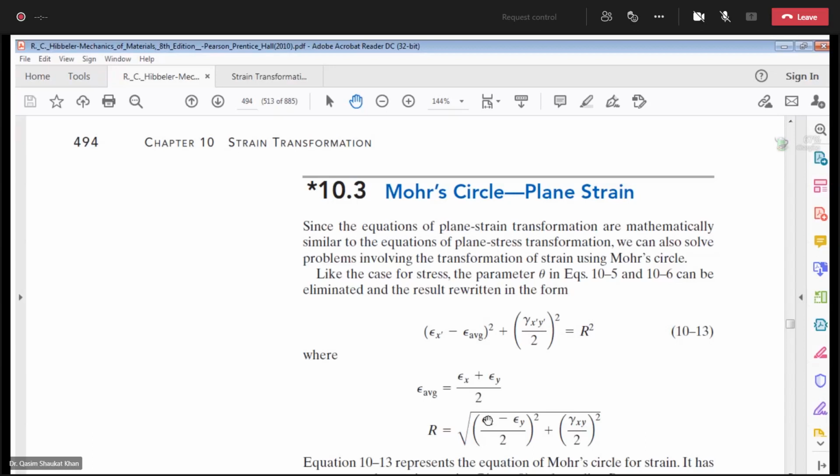Sir, 208.8. Okay. When you are drawing the Mohr circle, I would suggest you keep the answers in round figures, with no decimal place. So 209 microstrains. The radius, or resultant, of the Mohr circle is 209 microstrains. True? Yes, sir.